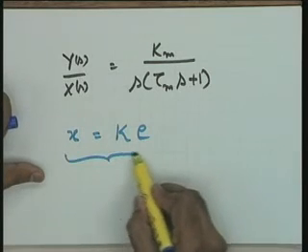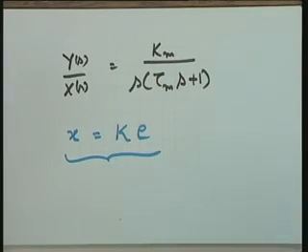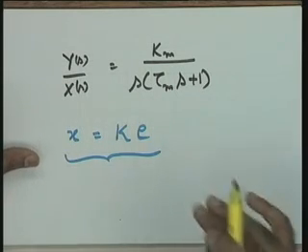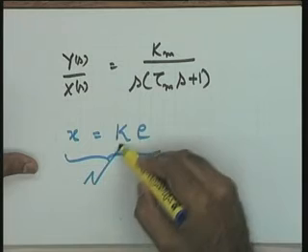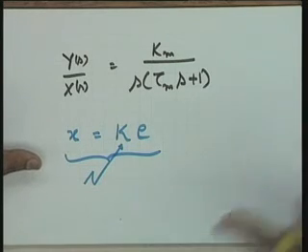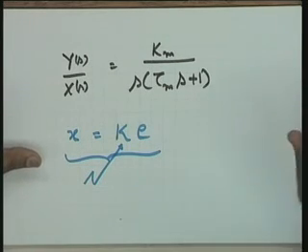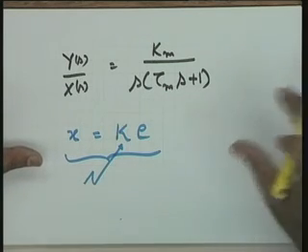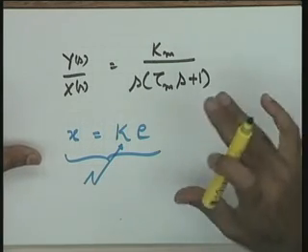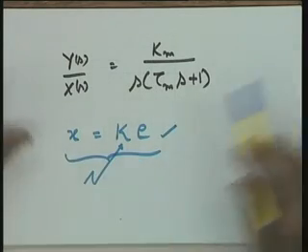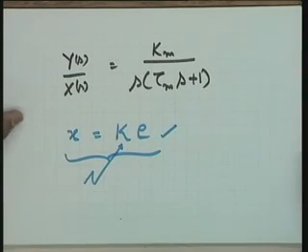You please see the assumption, not that it is not a dynamic device. There is a dynamics, but I am considering this to be a zero order system, assuming that the dynamics of this particular device is faster compared to this. Equivalently speaking, the time constant of the electro-hydraulic device is much smaller than that of the motor, and that is why we are neglecting it, and we are going to take this EH valve as a zero order device.